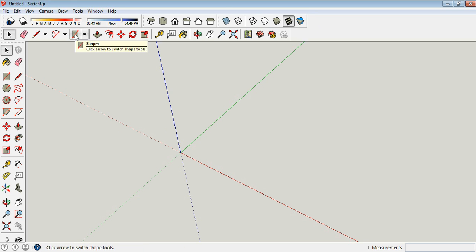For a start, we make use of the different tools down here in the standard layout. First one, shapes. For shapes, we'll do a rectangular shape. You realize that when I go to the origin, click on the origin, and pull it away, the dimension changes. What we want is a dimension of 120, 140. Enter.